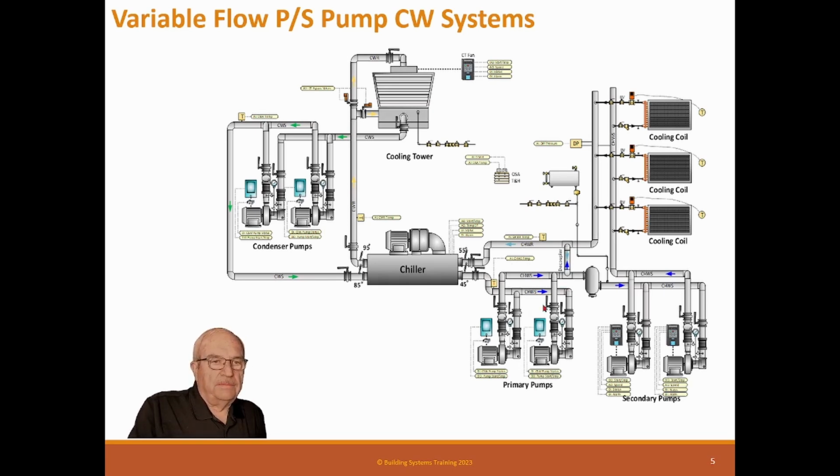This is, as I said, the primary, and this is the secondary pump system. Now, the expansion tank has on it here supply water, so it has a backflow preventer and a pressure reducing valve.